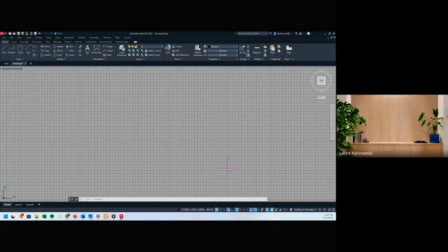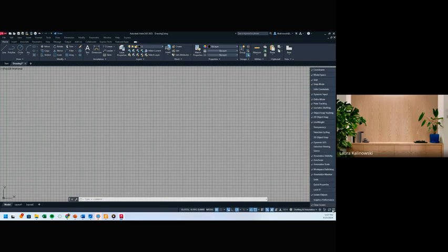Also on our screen, on the bottom right corner, you'll see something that looks like 3 horizontal lines. Sometimes we call that the hamburger, and that's for customizing. If we click on this, it pulls up all of the different things that we can use in CAD to create more toolbars for us. What we want to make sure is that we have on our coordinates all the way at the top. Make sure you have a little check mark next to coordinates. That's what this is down here. We're going to be using that today. So make sure that you have coordinates check marked on.